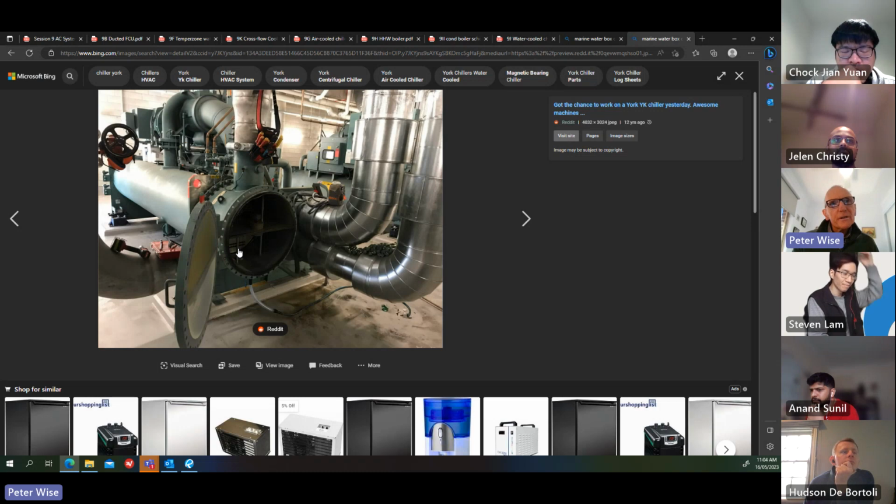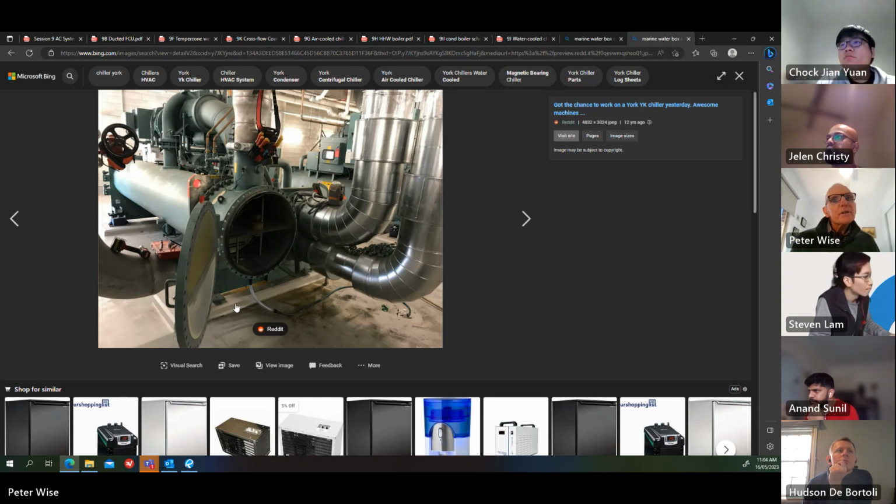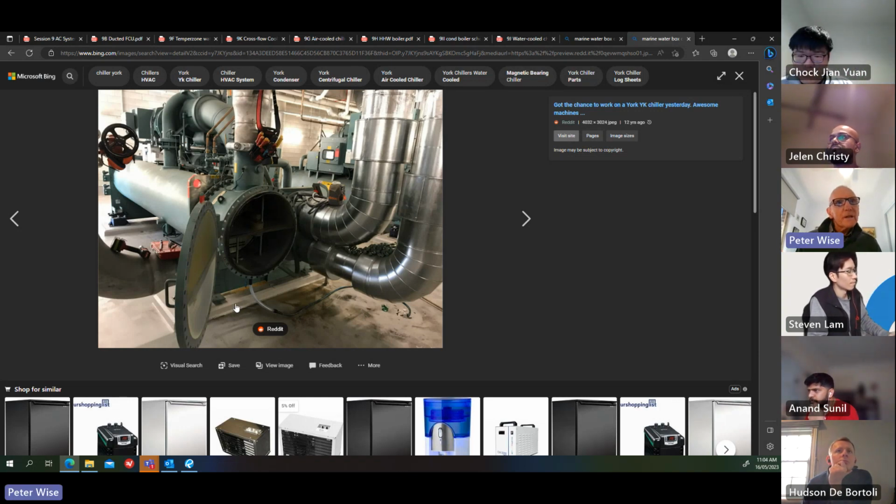And you can see the tubes inside there. Can you see those tubes there on the tube plate or tube sheet? And up the top as well. It's a bit dark, but they've got to clean them out, and they use a rod to push through all those tubes and get the muck out that's collected over time from the condenser water system. If you have a cooling tower, it's essential to do that every 12 months. If you've got fluid coolers, which is probably unlikely, you wouldn't have the same issues because it's a closed system.